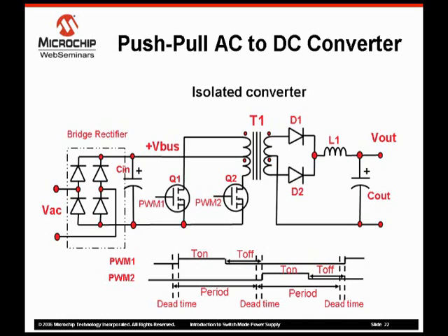One important consideration is that the push-pull design is sensitive to flux imbalance due to slight differences in current flows into the transistors. Flux imbalance can cause flux saturation. It is highly recommended that current mode control be used to monitor the current flow through the two transistors.